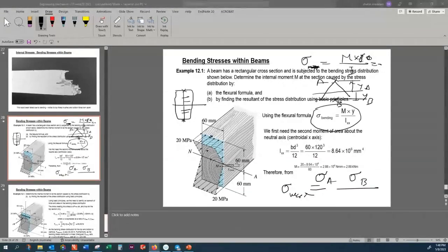When I ask you what is the maximum normal stress in a cross section, and the cross section is a composite beam, the question is whether the top point is critical or the bottom point. And the only way you can answer this question is by finding the neutral plane. So the point which is farther from that neutral plane is most critical.